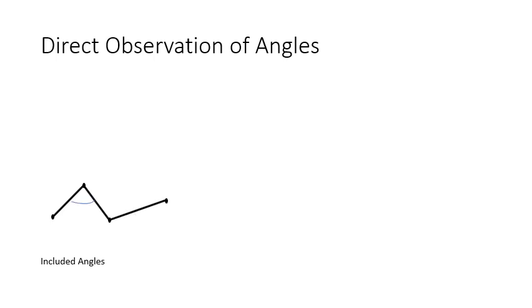Then the third survey line, you can measure the angle between the second and third. Another survey line, you can measure between the third and fourth survey lines. So in this way, between each and every survey line, we can measure the included angle. Even though we are doing the traverse with the angle method, we need to know the orientation of the entire feature. For that, we need to get a bearing of any of the survey lines.